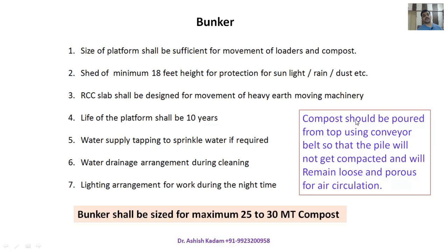When these earth moving machineries go inside, they are basically compacting it. If you are compacting the compost, then the density of the compost will increase, and the holes, the porousness, or the gaps in the compost material will get removed, they will get plugged. Then even if you are supplying air at very high static pressure, using very big fans and blowers, it will not help to have proper air circulation.